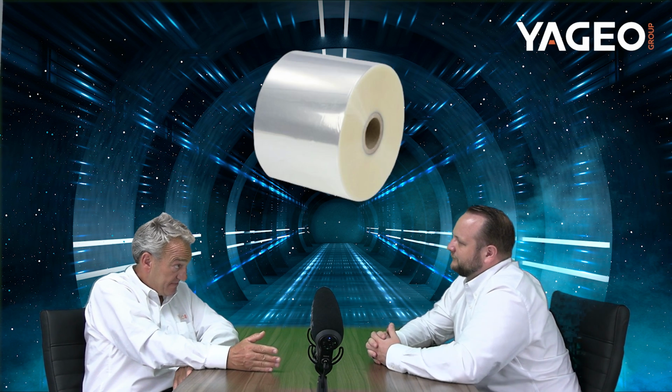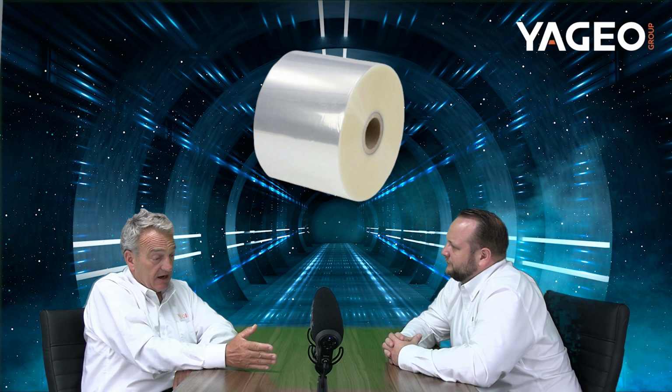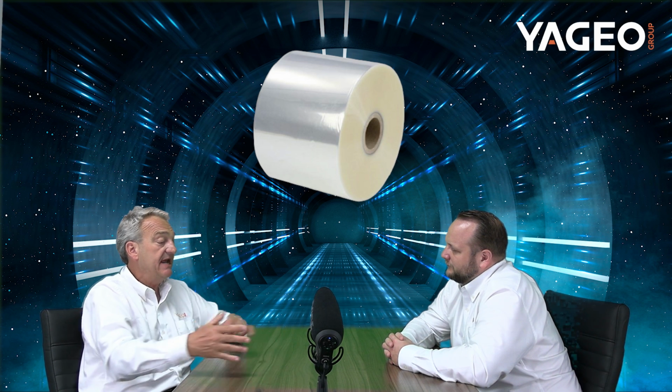So when I think about a film capacitor, we talked about the structure of an aluminum electrolytic. We talked about the structure of an MLCC. When I look at the structure of a film capacitor, what does that look like on the inside? So again, let's go back to our starting point, which is saran wrap. A film cap would be really, if we take 2 layers of saran wrap, and each layer of saran wrap, we apply a very thin amount of metal deposition.